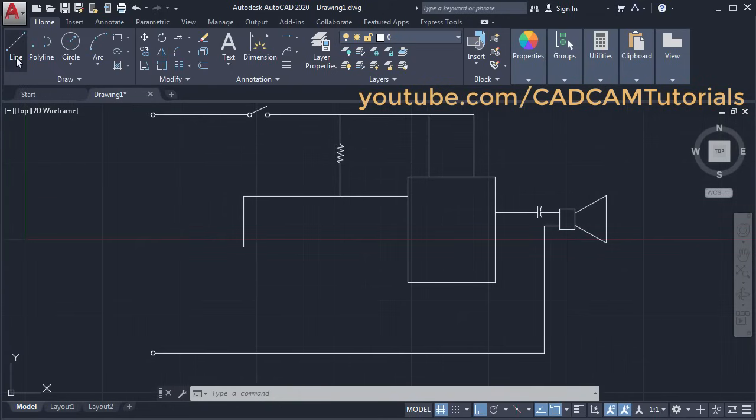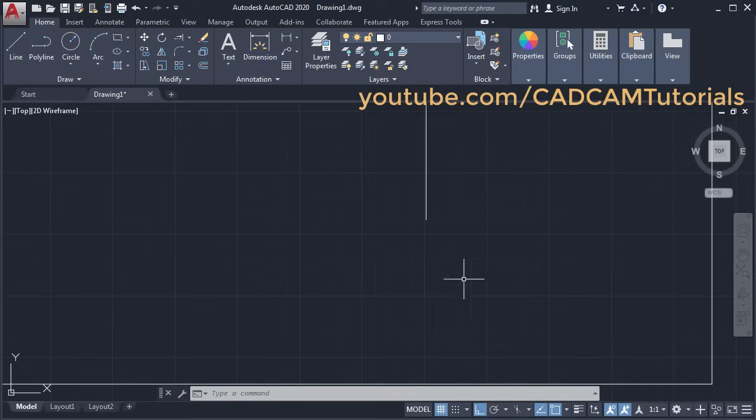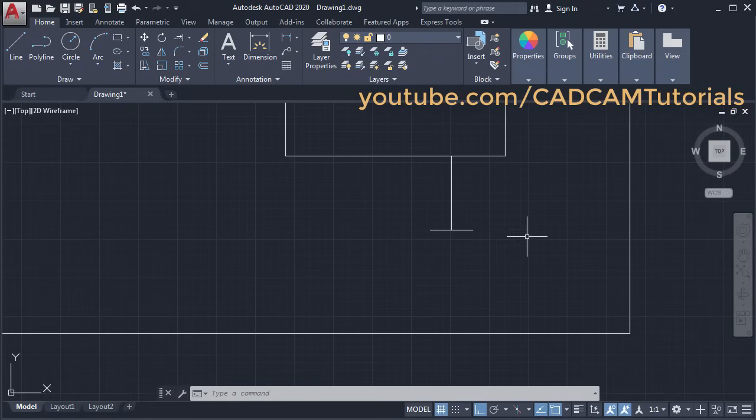Click on line, then take your cursor to this intersection point, take it below, click, take it below and click, enter. Then zoom there, then again click on line, take your cursor to this endpoint, take it outside and click, take on this side and click and press enter.